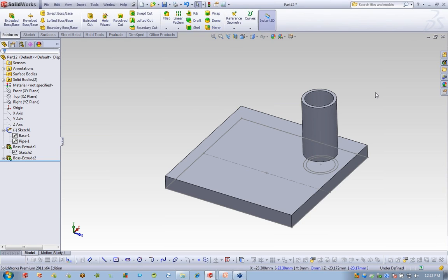Now I've seen several customers that do part layouts, and they just create a single sketch that contains all of the information needed for the layout. The difference between this approach and that approach has to do really with the relationships between the separate features, I guess I'll call them. I didn't have to worry too much about the relationships between the center point of those circles and the rest of the geometry. You actually create less relationships by creating these blocks.